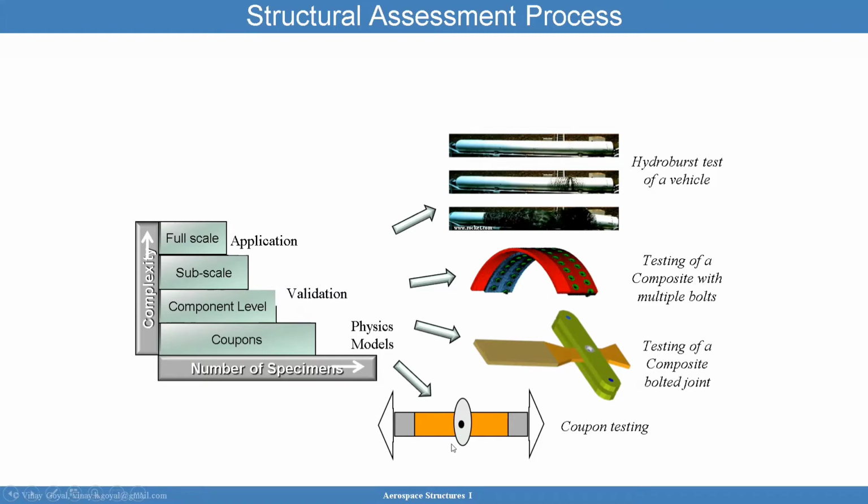And so if your manufacturing processes are qualified all the way from the bottom up, then you are gaining confidence. For example, say that when I'm manufacturing these coupons and I'm using the cure cycle for these coupons, and the cure cycle happens to somehow cause dry plies or causes too much resin, whatever that might be, you will know quickly what's going on, and you can rectify the cure cycle to get a better product.